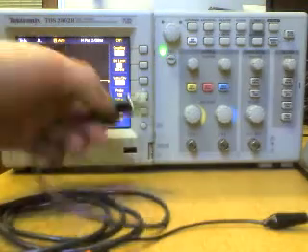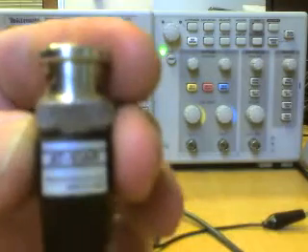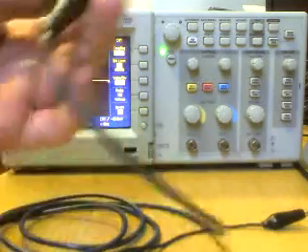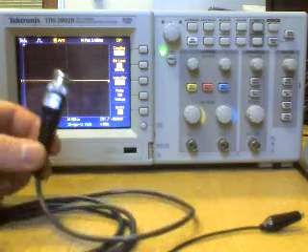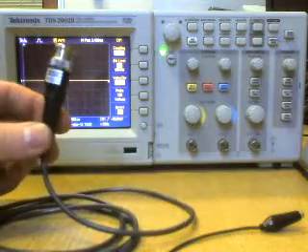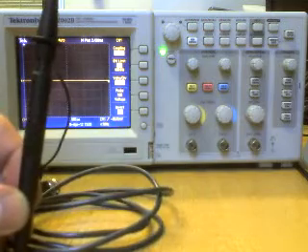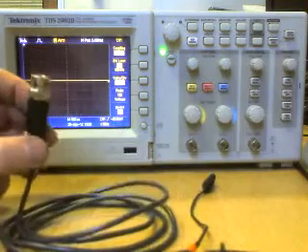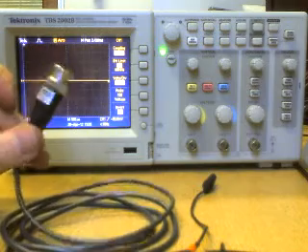You do secure measurements. Now these oscilloscope probes here, if you zoom in on this one, I don't know if you can see that, it's a ×10 probe. And what we mean by ×10 is it has a ×10 attenuator. Now this one's ×10, so if we have 1 volt at this end, it gets attenuated by a factor of 10. You end up with 0.1 volt at this end. So you end up with 100 millivolts if you input 1 volt. Odd. Why would you want to do something like that?